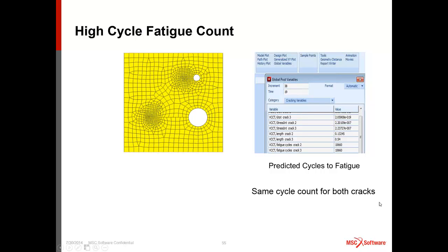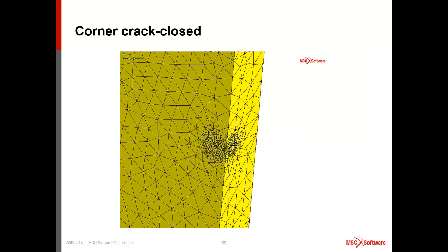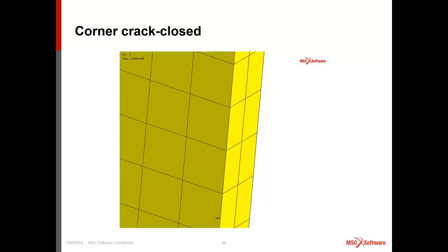So what one would have obtained here, and if you do the appropriate scaling, you'll get a number that basically says if my crack was initially 0.1 in length, for my crack to grow to 0.13245, it would have taken 10,660 cycles. That's the information that you obtain. So we obtain the incremental fracture mechanics quantities. We look at the incremental crack growth, and we determine the cycle count based upon that.